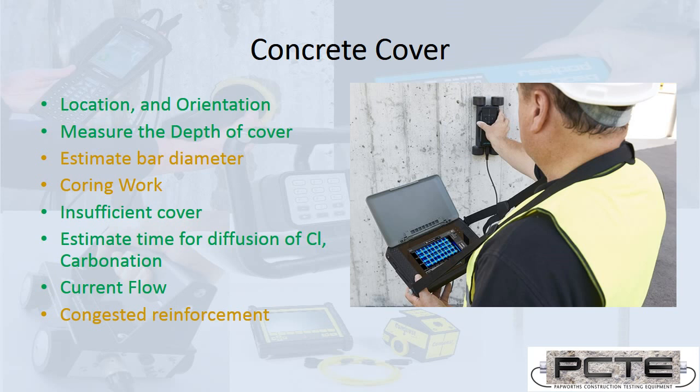They're ideal for locating regions of insufficient cover. They're ideal for giving other depth inputs to design life calculations. So if you know the diffusion rates of chlorides and you know the current depth of steel, once you've got the two, you can form information there.